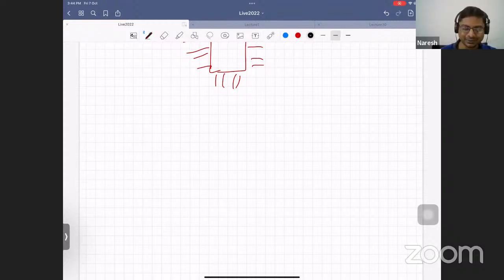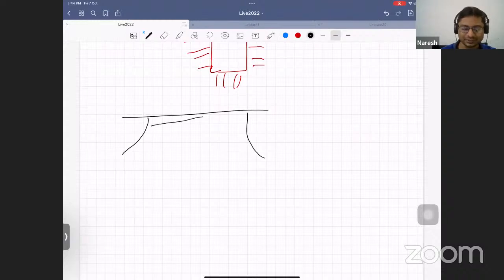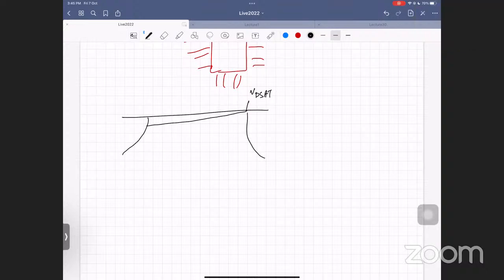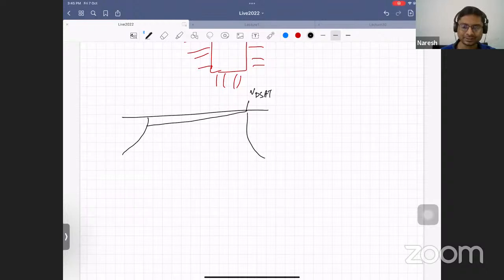So the reason it happens is, let's say you're talking about a MOSFET like this, and you have this pinch off, right? Now the question is, if I think about this voltage, what is VD sat when this pinch off just happens? In the traditional long channel MOSFET, this will be VD sat, correct? At VDS equal to VD sat, it will happen. You agree with me, Lakshmikanta? Yes, sir. So now what we're talking about is voltage greater than VD sat, correct?